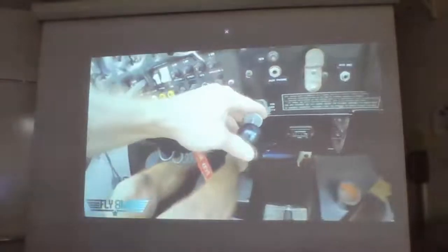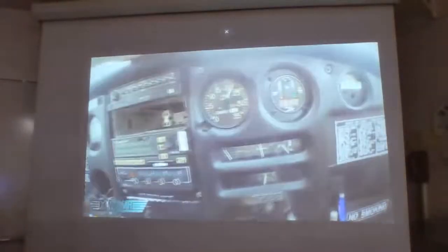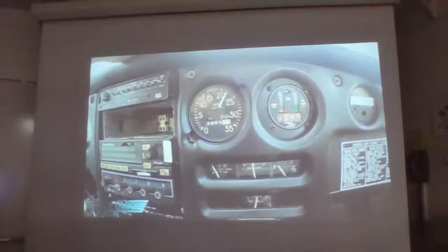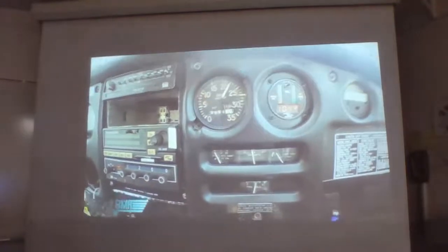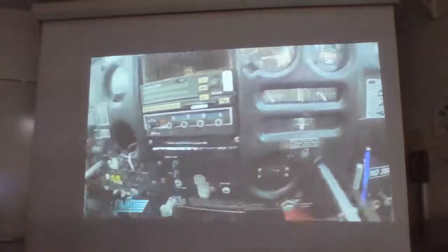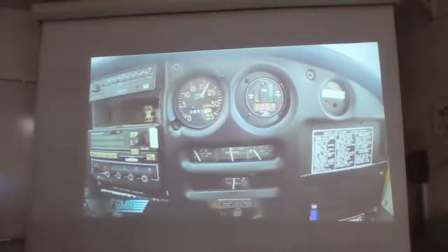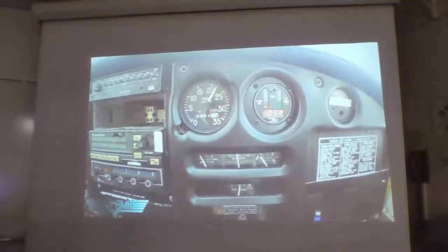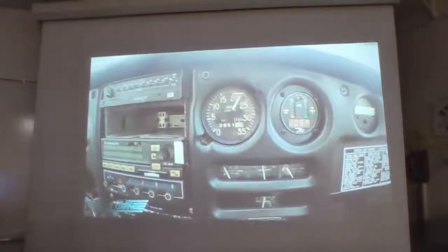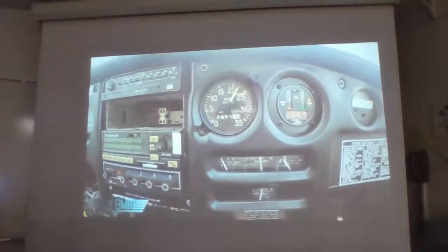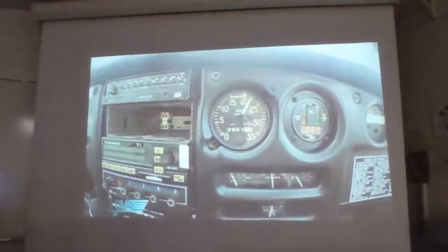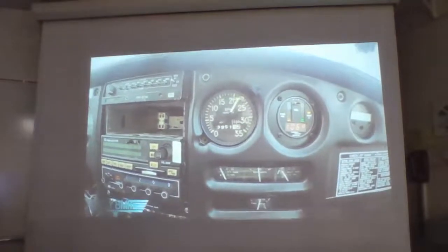This is full power, guys, all right? That's everything she's got. Now, obviously, our RPM is a little bit low here, 2,200 RPM, 2,250 at most. That's because we're just sitting here stationary. If we were in flight with full power, we'd probably be seeing somewhere around 2,600, 2,700 RPM. So the engine is making full power here, but we're not seeing the full RPM because, of course, we're stationary. This is called our static RPM, and static RPM is a little bit lower than the RPM